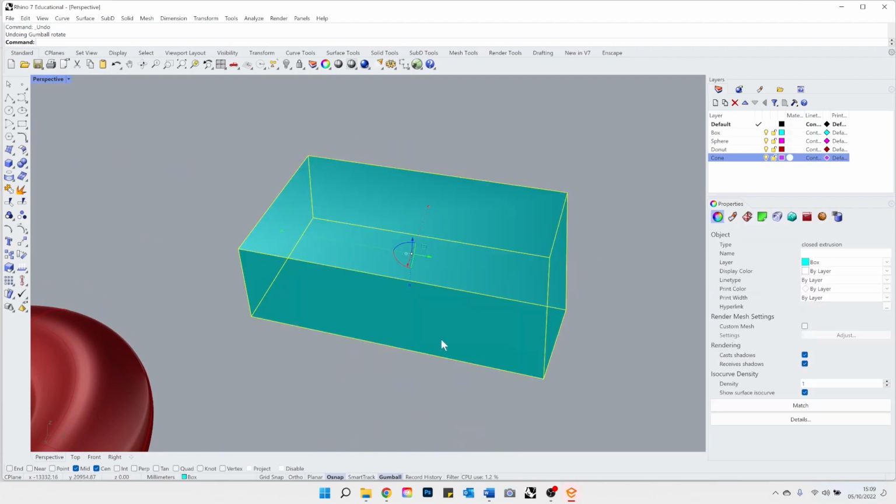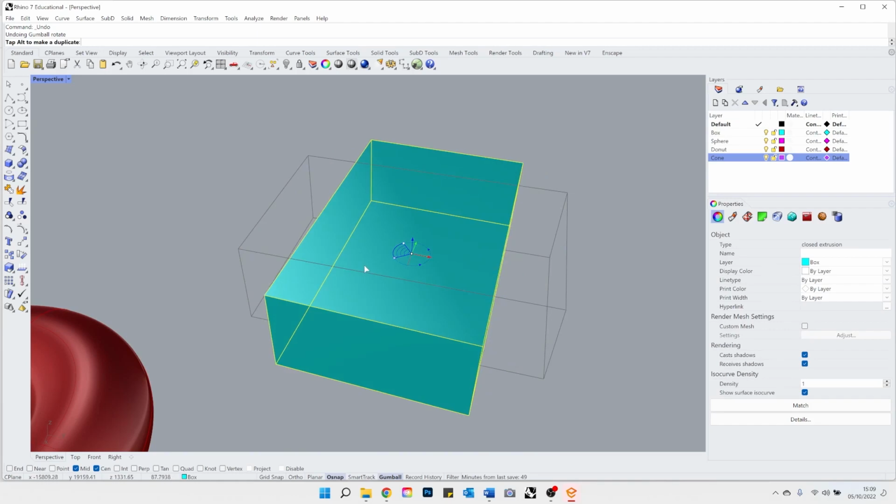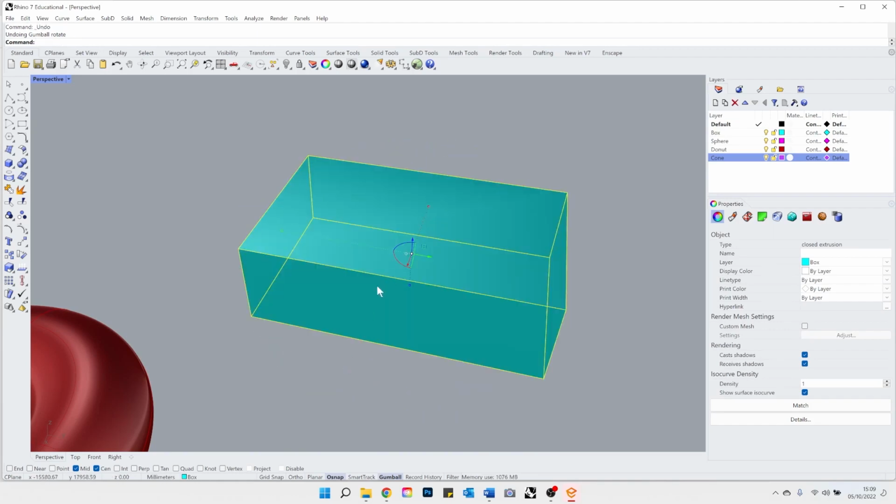I'm expecting some of you don't have that much freedom of rotation. It could be because you have Ortho ticked on. So the second option on the bottom part of the screen is Ortho. Ortho is the same as, for example, you might have heard of it or used it in AutoCAD. So it snaps to specific angles. As a standard, it will allow you to draw or rotate your object exactly onto 90 degrees. You can manually set it to any other degree.